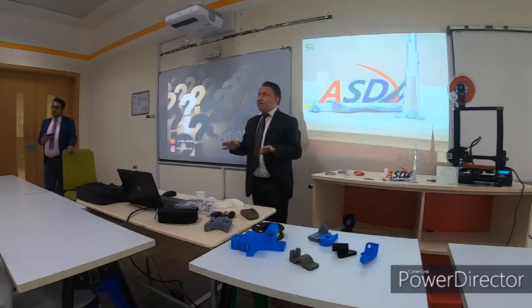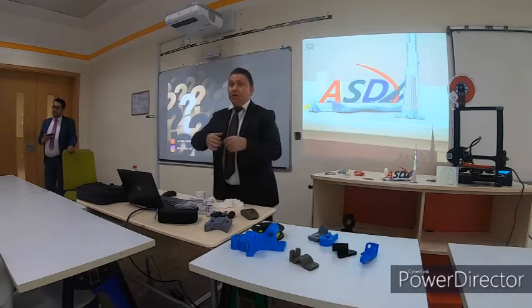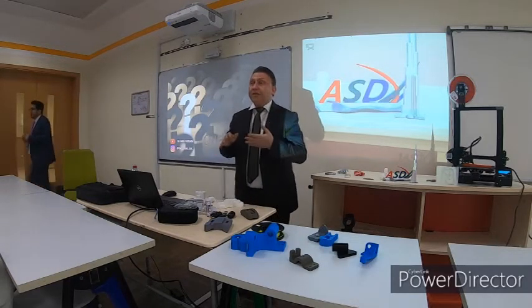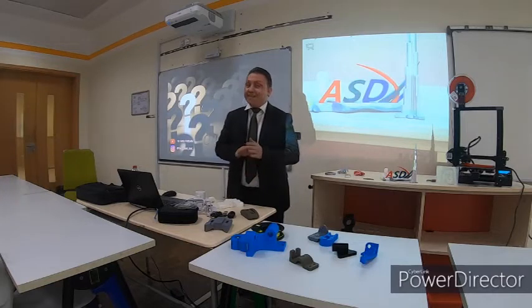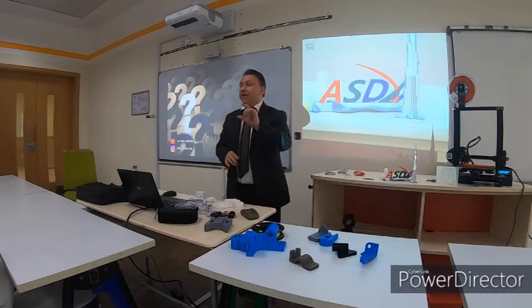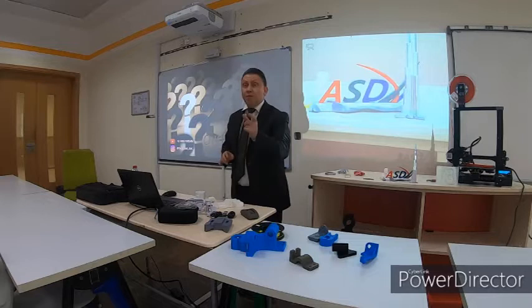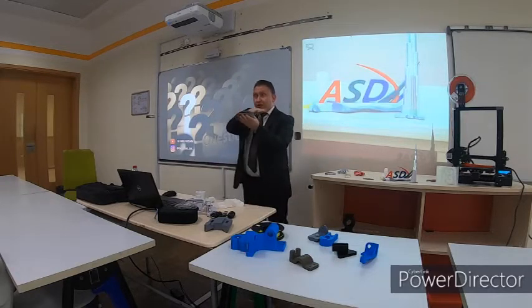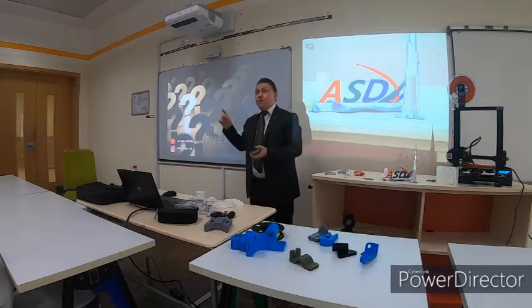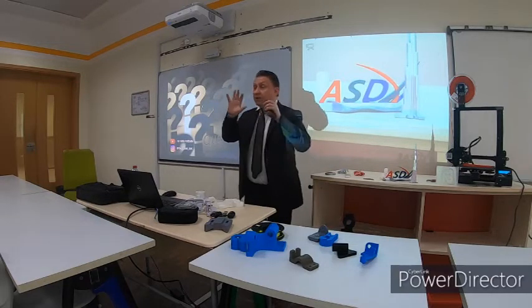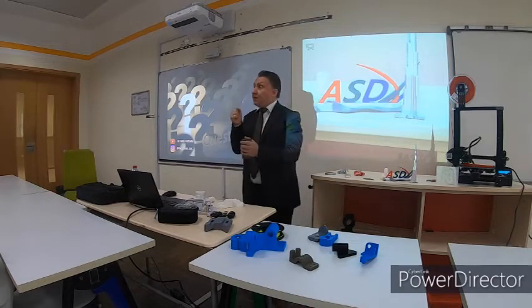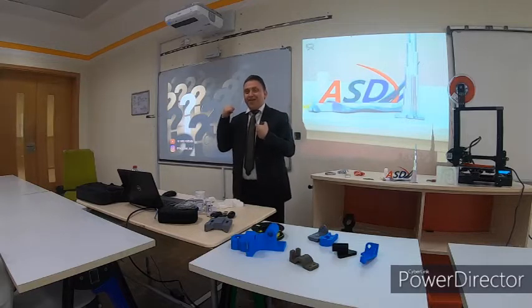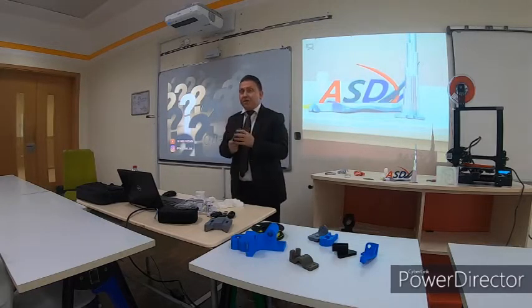Yes. See, I will answer your question. For mass production, it's not recommended. It's only for prototype. The behavior of the plastic from an injection mold is totally different from a prototype. This one, the structure is built layer by layer, while the injection mold injects the plastic simultaneously into the whole cavity, one time. That's why the rigidity of the plastic differs, because I was working as a plastic designer.